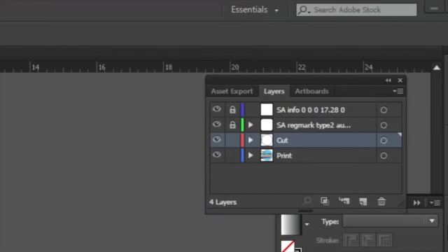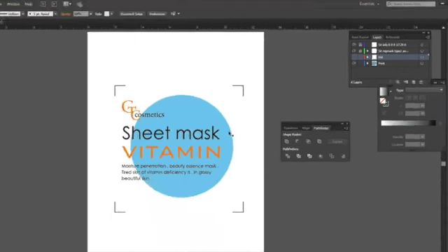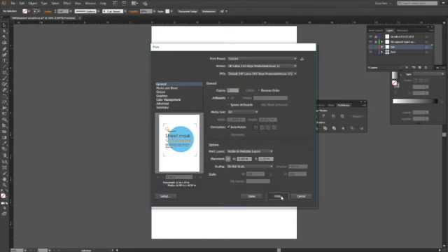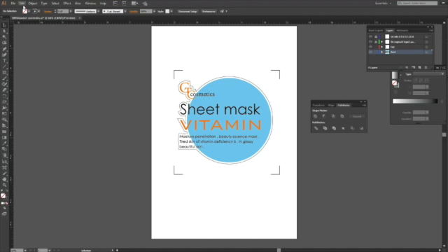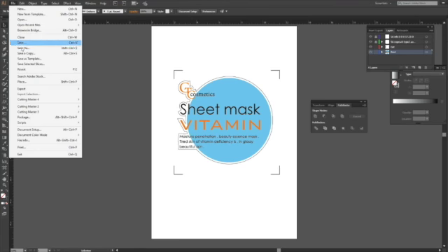The design is ready for printing, but first we have to disable the cut layer so it doesn't print with the design. When loading the print onto the FCX 2000, getting the correct orientation is essential. The easy way to determine this is by opening up the Cut Plot window for Cutting Master 4.